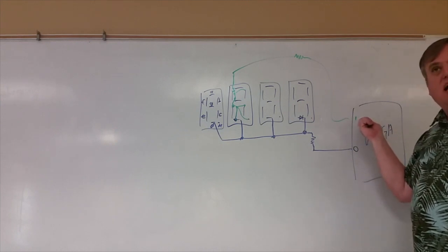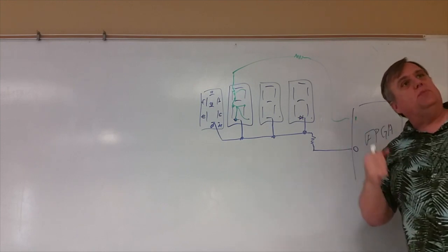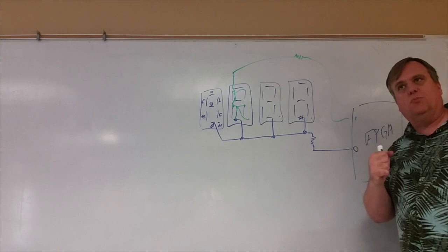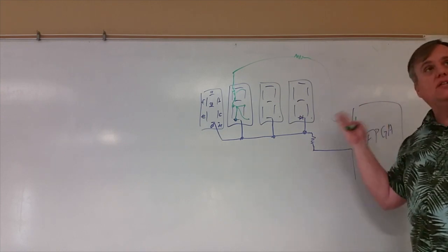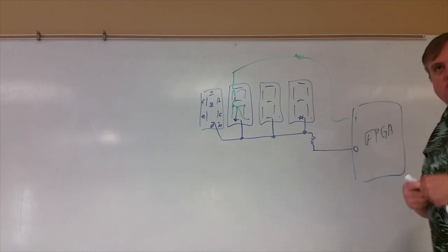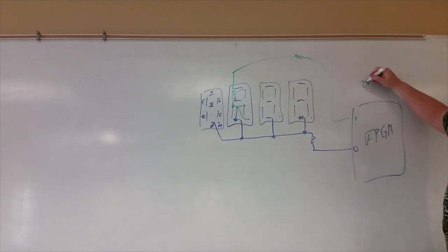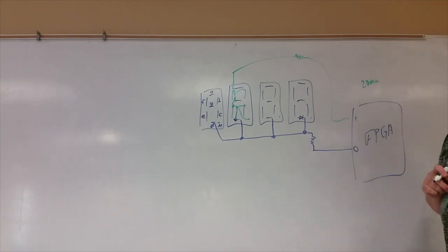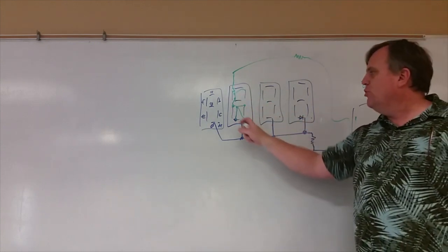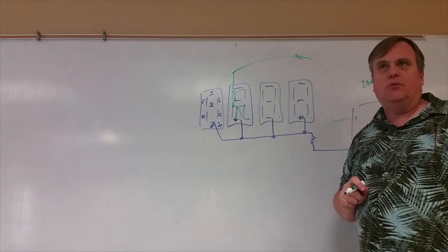This is an output of my system. As an output of the system, it can supply a maximum of 1 pin's worth of power, which on most of these output gates for our systems, it's a low voltage setup, which means you're somewhere less than 20 milliamps. That is going to have to flow through 8 devices. This is called the fan-out problem.